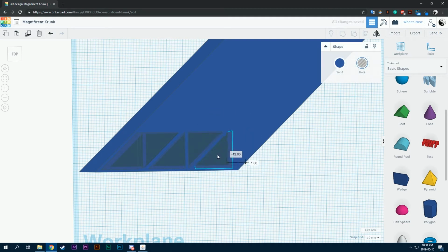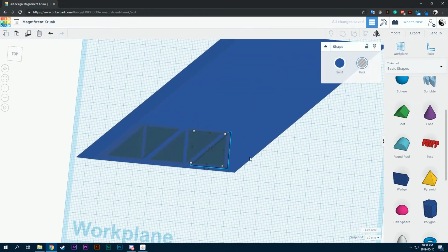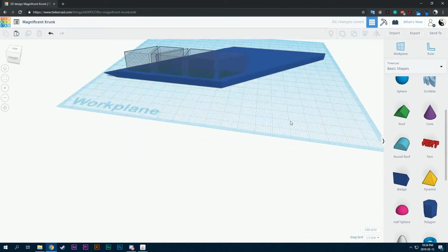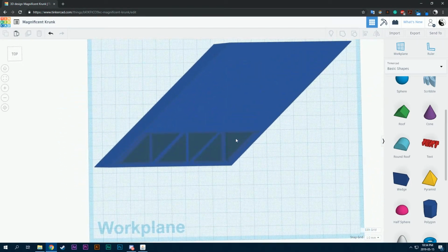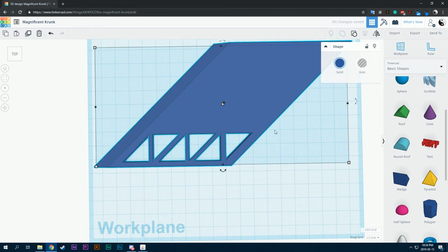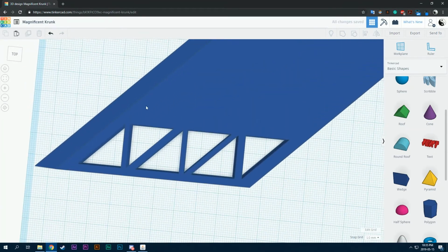So you just keep rotating it around until you get around this stage, and maybe you can do one more. So let me try. Rotate it, and yeah, we can do one more. So once you have this type of basic shape done, you can just click on your fin, click on all 6 of these objects, just group it again, and it'll cut all of the holes out. And you see how these things bridge?